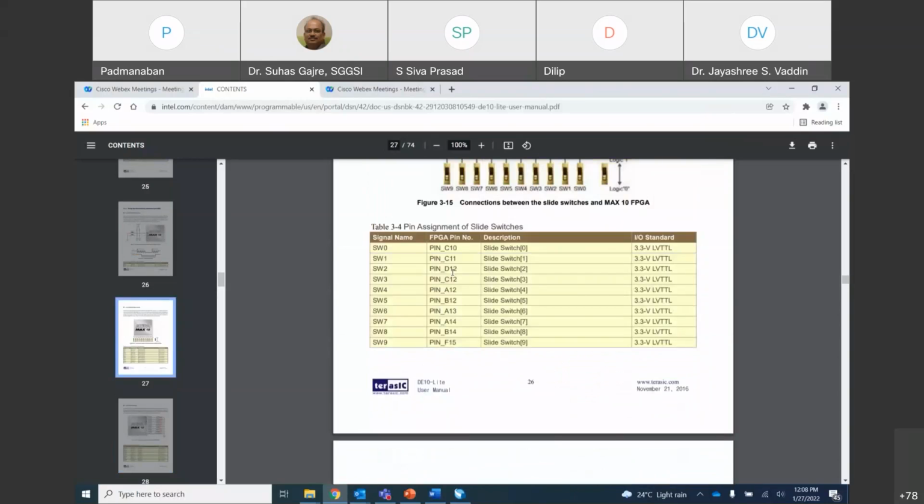So how do we go ahead? Let us explore that here. You can do everything up to compilation and generating the SRAM object file; those steps are common for everyone. Only the implementation on the board, I will do traditionally with the board that I have. But in the second demo, I'm going to show you how that could be done virtually. After the demo, you can also try the virtual labs with the remote console, where you can connect to the board and check the functionality. Right, let us explore this right now.